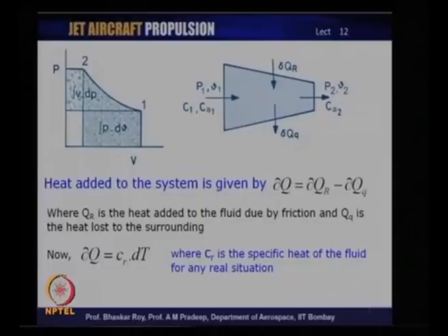We know that specific heat for a constant pressure process is known as C p. For constant volume, it would be called C v. This is a process which is neither constant pressure nor constant volume, some real process, and we are simply calling it C r for the time being. So, the process that we are seeing here is a little more realistic process subjected to a compression.